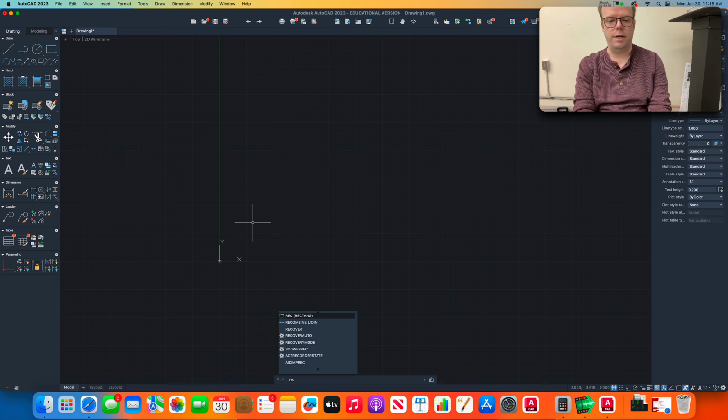So we're going to type L-I-N-E, which is the line command. Or you can just do L. L is the abbreviated version for the line command. So L, enter. If I click the line under draw, that's cheating. Don't do that. We're going to type. So type line, or L, and hit enter.